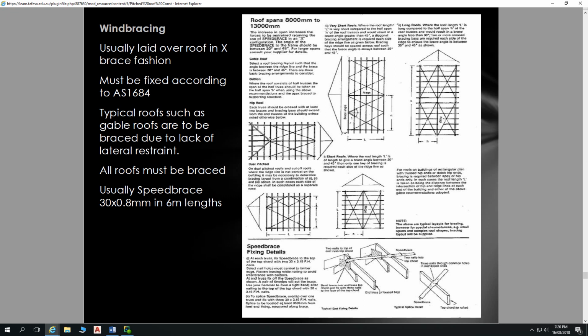The reason for this is that these timber members that come in at a 45-degree angle provide bracing of that roof end. Whereas with a gable end roof, you don't have that bracing component of those pieces of timber that come in at an angle, so you need to specify more bracing in a gable end roof.